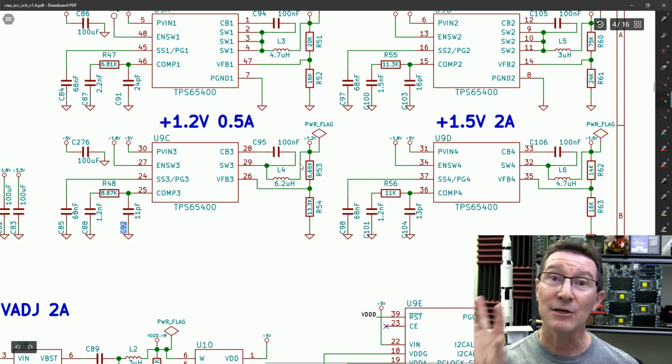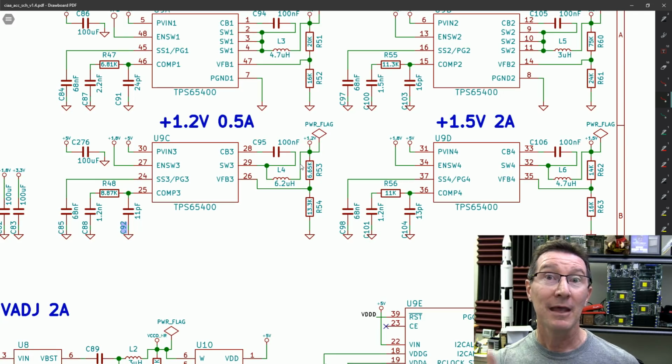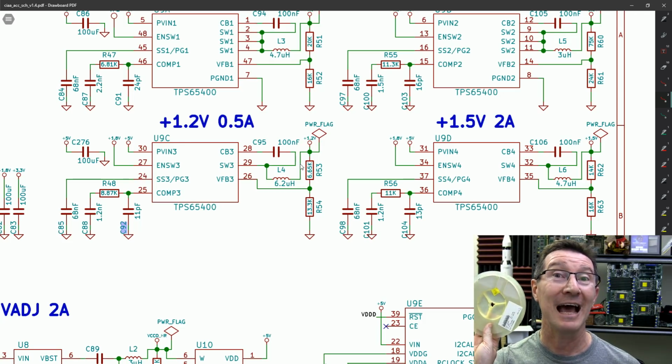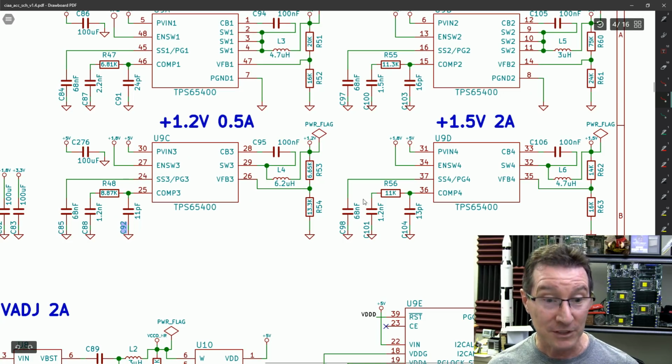And here's the next thing, with value consolidation, it can actually be better and cheaper and more beneficial to use more resistors in your design than to choose the right value and have to get another complete reel and have another individual BOM item. For example, this is a classic example of it here, where you need a specific value to meet your tolerance of your 1.2 volt voltage rail here.